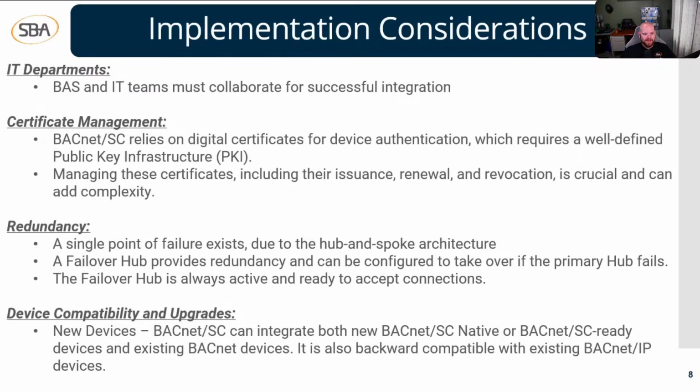All right, now let's talk about some implementation considerations. These are the things you're going to have to think about before you start trying to take off with upgrading to BACnet Secure Connect. Consider these things first. IT departments, and again, this is what we were talking about a little bit ago: BAS and IT teams must collaborate for successful integration when we're upgrading to BACnet Secure Connect. I've got a case study in here that we're going to take a look at in a little bit that shows that collaboration is going to be very, very important between BAS and IT teams.